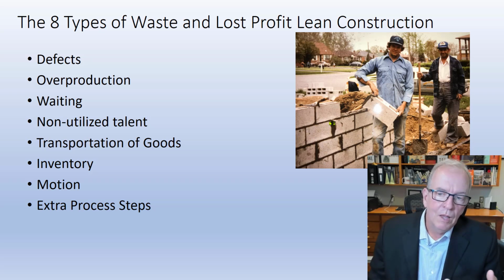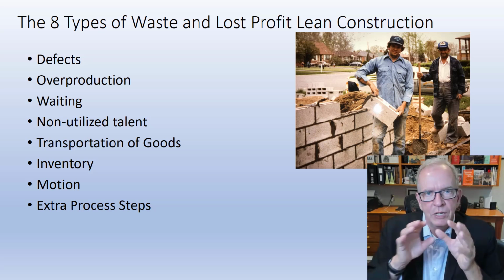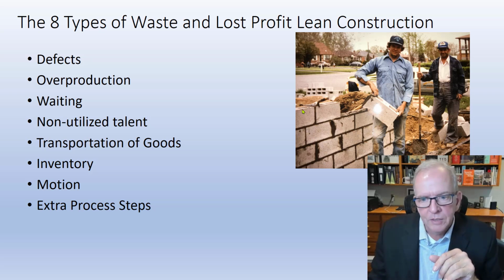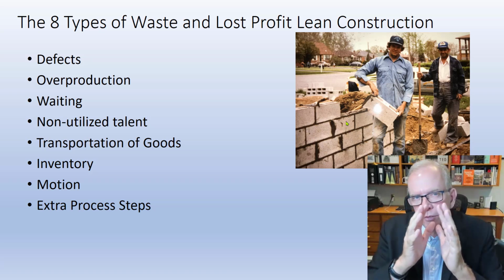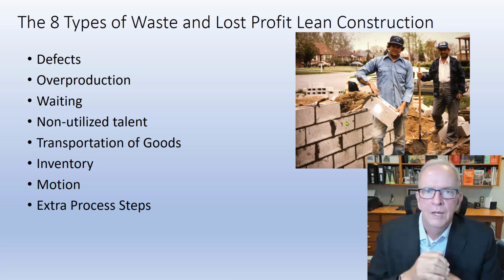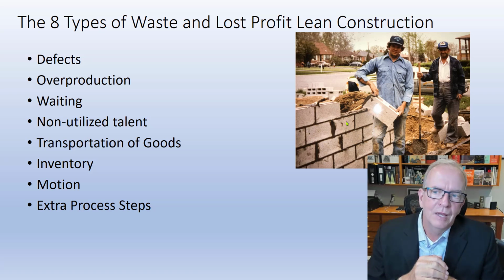Well, luckily I only had the backup block on, but basically what happened was I remember having a coffee and watching these joints slowly opening up like a little crack. It was hydrostatic pressure against the wall that was slowly moving the wall. And of course, that basically meant that the whole thing had to be taken down. It pretty much fell down by the time the water did its job on it.